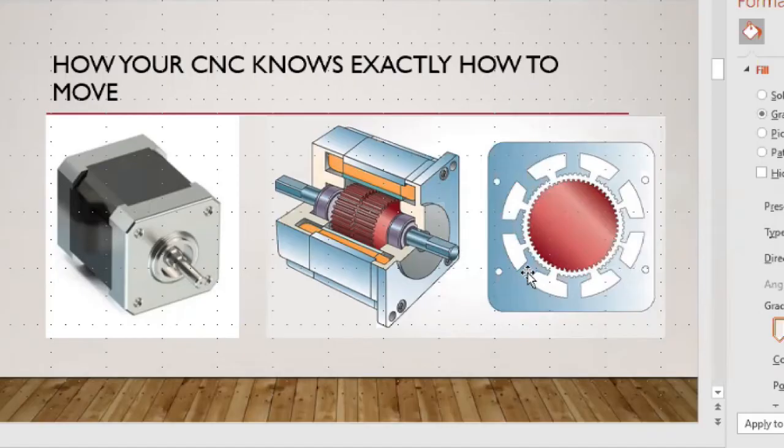And typically it'll be coils that are opposite each other that will be charged. And what that'll do is create a negative pole or a south pole or a north pole magnetic field, which pulls the armature. It pulls the little teeth, which are magnets, in line with the opposing field, meaning you know that a north pole is attracted to a south pole.